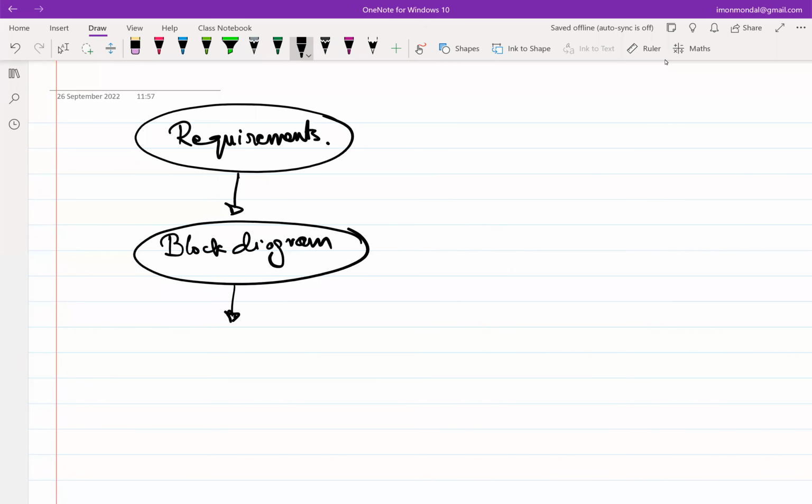model. When I say incremental model, what I essentially mean is that obviously this is a circuit design course. This is not a generic design philosophy. So now if you have to realize the block diagram, you are realizing the block diagram using certain control sources. And in our case, the only control source that we have at our disposal is a voltage controlled current source, also a transistor.